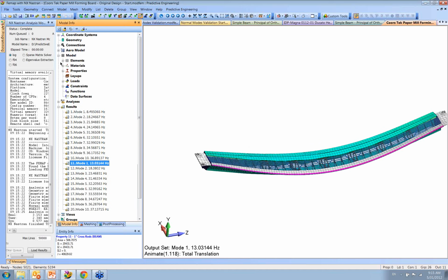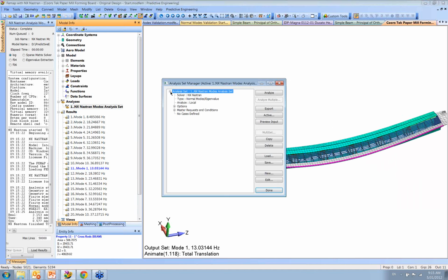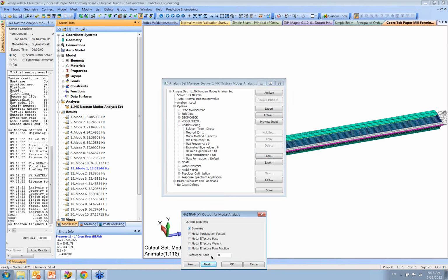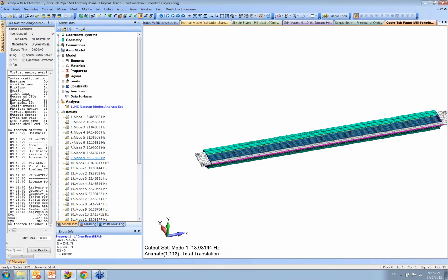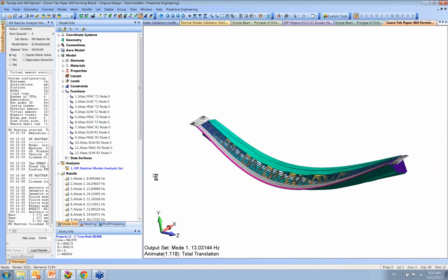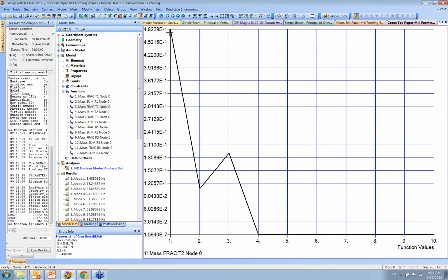And this the same way. You can look at the mass participation, and it's quite useful too, because it just confirmed where. Oh well, I'll just take that. And go into functions and the direction of interest. Let's look at y going up. And you see the first mode is dominant up there.